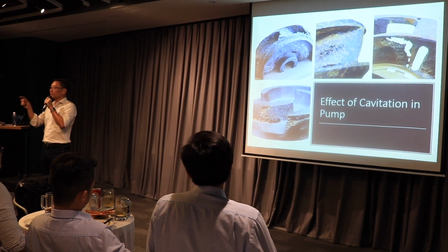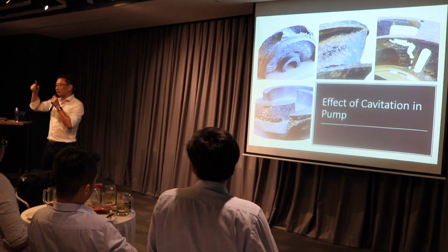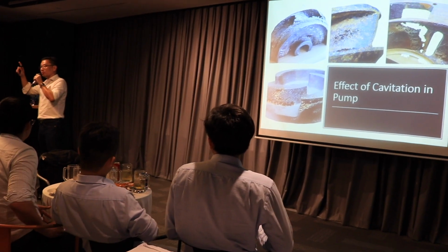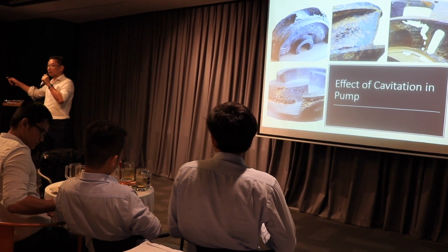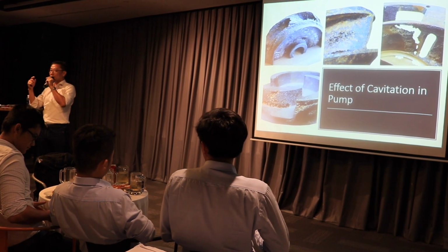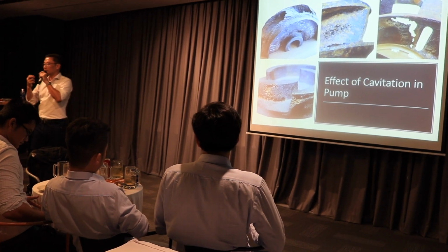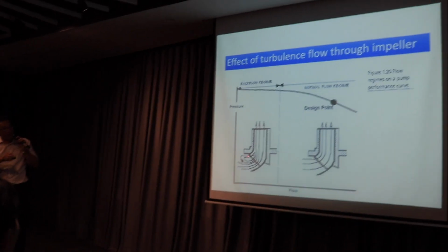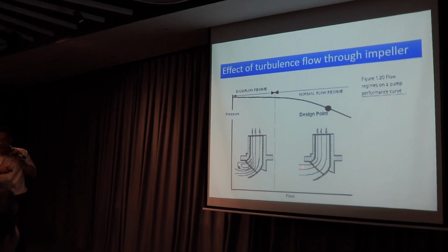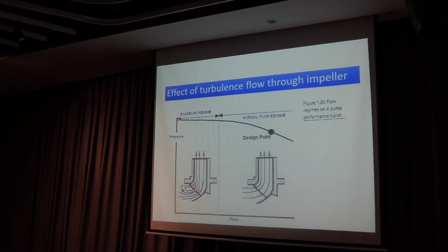It's because of the suction pipe. The NPSH, net positive suction head required and available, they don't match. When they don't match, they create millions of bubbles. So what happened here is that instead of having this much space for the water to come in, it is now reduced to only so little.